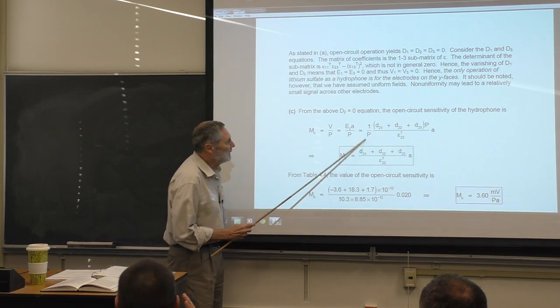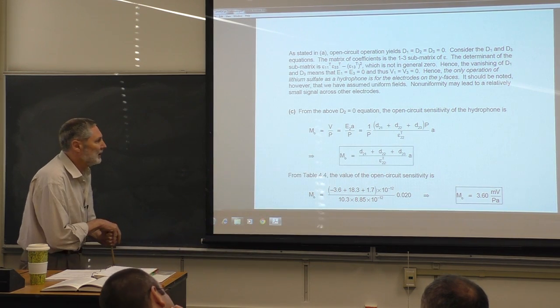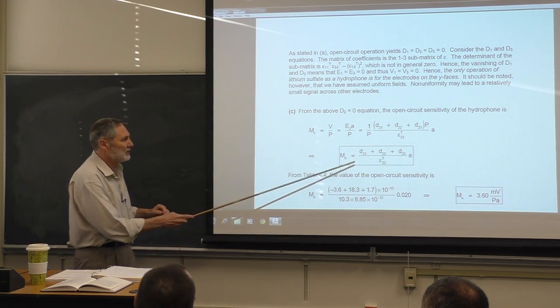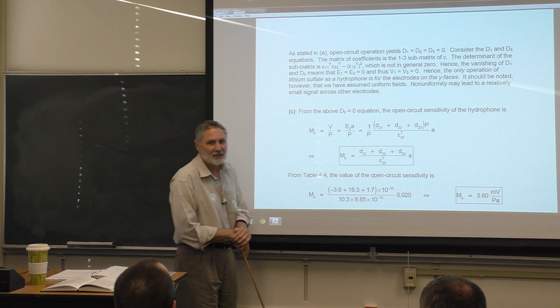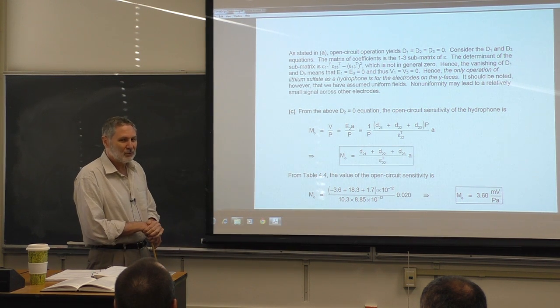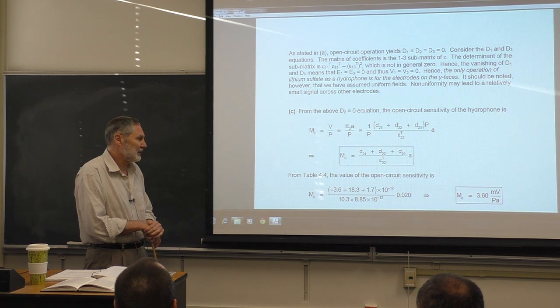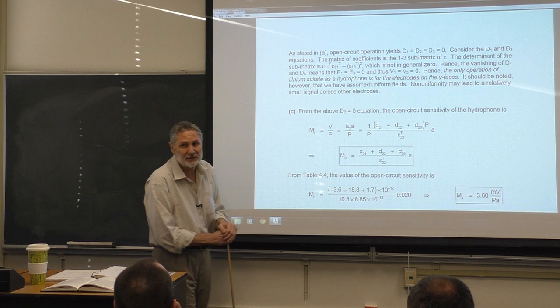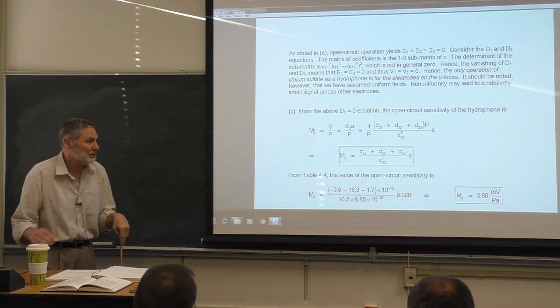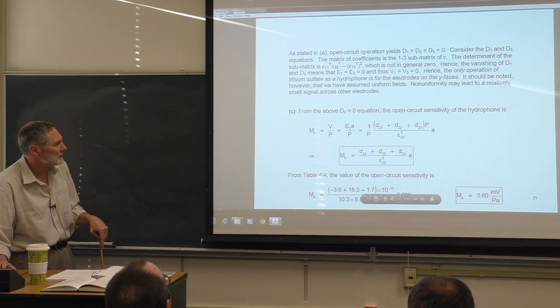So they cancel. You can see the linearity there, and we've got now a formula in terms of our material and constants and the dimension here. And that's the whole theoretical point here, in transducers, to be able to theoretically derive this. Now you can plug numbers in and see if it's reasonable to use as a hydrophone. That's what we'll do next, it looks like.